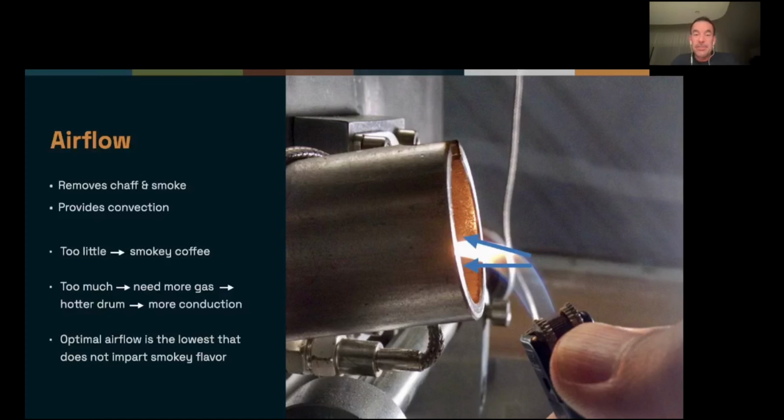In a machine that has inlet temperature control, in other words, instead of managing the gas with, say, 80% gas, 70%, 60% gas, there are machines, like, let's say IMF and Civets, where you can control the inlet temperature directly. So you can tell it, give me air that's 360 degrees Celsius, 340 degrees Celsius. That is the temperature of the air entering the roasting chamber. In those machines, increasing airflow will accelerate heat transfer. So in those machines, the heat transfer is temperature times airflow.